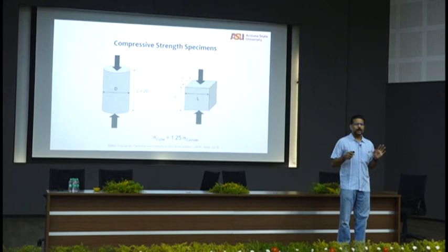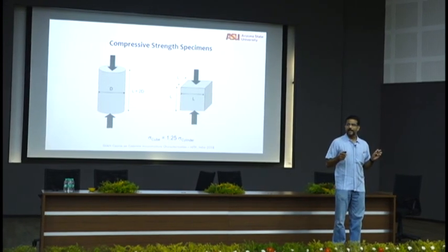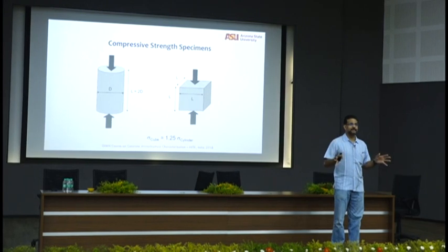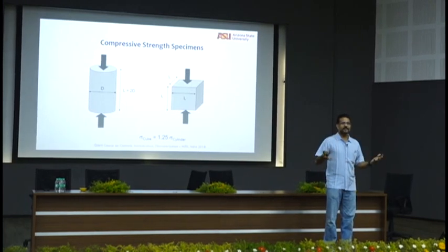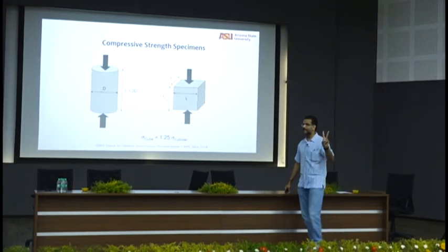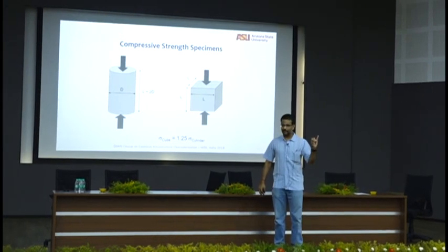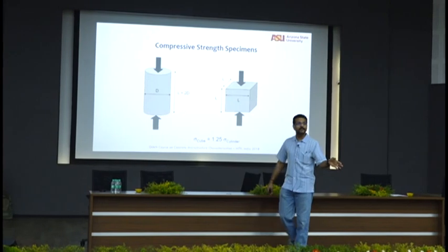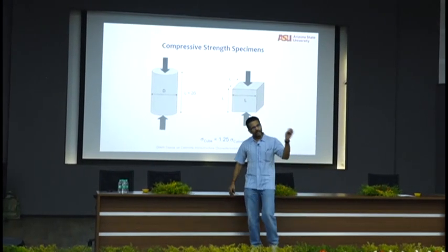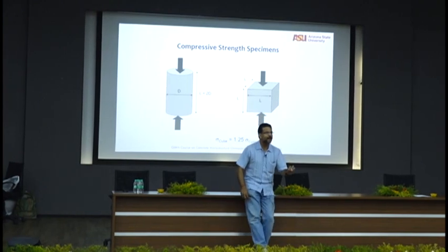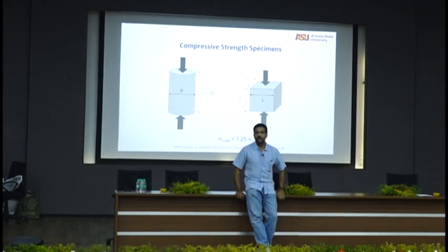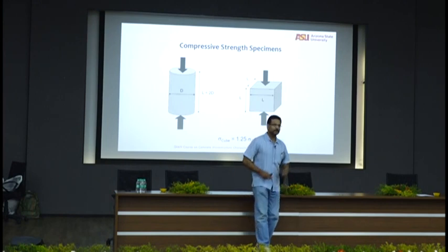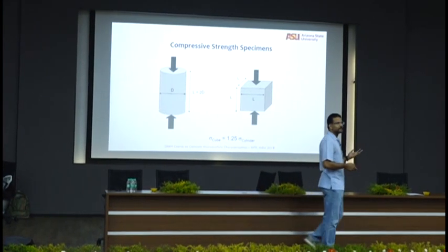How many structural engineers? If you do any analysis in a finite element program of a concrete structure, what are the only two things that the analysis program will ask you? Young's modulus and Poisson's ratio, that's it. Young's modulus and Poisson's ratio are the only elastic parameters that you have which are material properties. When it comes to thermal properties, then you have thermal conductivity. With electrical properties, you have electrical conductivity. Those are all material properties. Strength is never a material property.